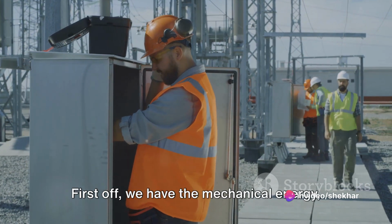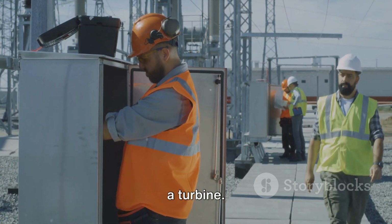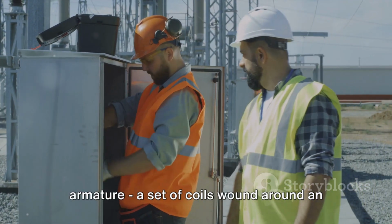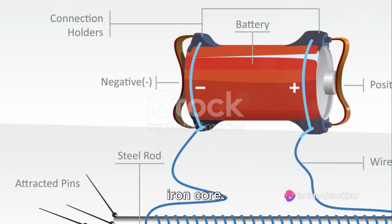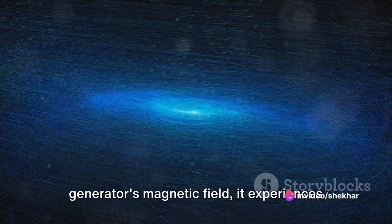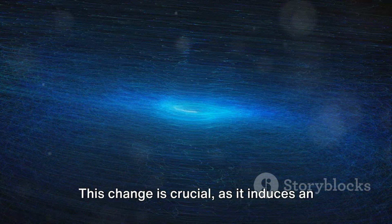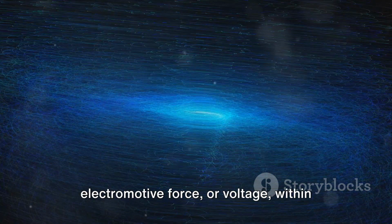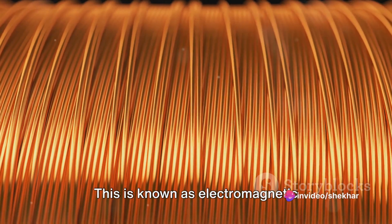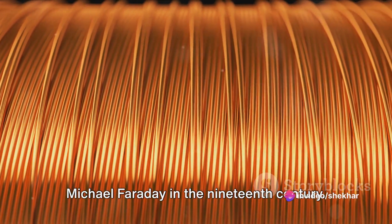First off, we have the mechanical energy, often provided by a rotating machine, like a turbine. The turbine spins the generator's armature, a set of coils wound around an iron core. As the armature rotates within the generator's magnetic field, it experiences a change in the magnetic field around it. This change is crucial as it induces an electromotive force or voltage within the armature. This is known as electromagnetic induction, a principle discovered by Michael Faraday in the 19th century.